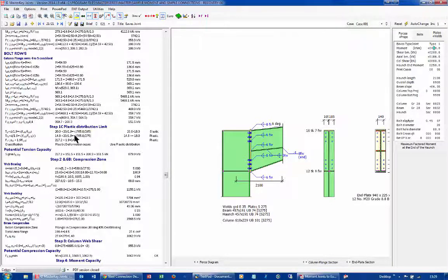And if I just pull my force diagram in here, here it comes. In this case, we are pretty inside the elastic line, except for these rows, which are probably not going to be considered anyway as part of the ultimate design, but these would be allowed to go plastic, whereas these are being limited by their proximity to other rows. But they all have to be balanced against the column in compression. The compression of the rafter, the compression of the web, all these. So the beam compression and the column web compression need to be considered.